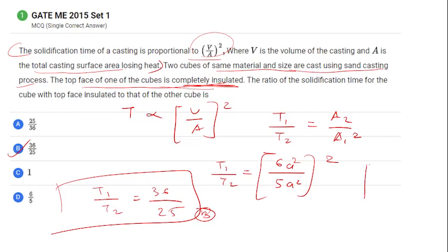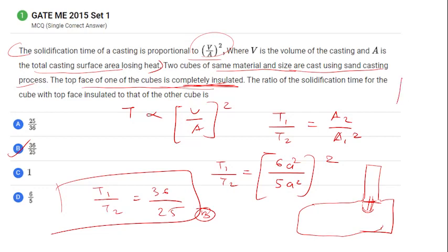Wait. This is your riser. Suppose this is your casting. Two types. This is your top riser. You are saying that this is in contact with molten metal at the same temperature. So see, whenever they give a question, they will tell you if it is in contact of molten metal or not. None of the questions have mentioned that, right? They are just asking there is one riser, and they are not telling you not to consider this side. Only take it if they have given that.